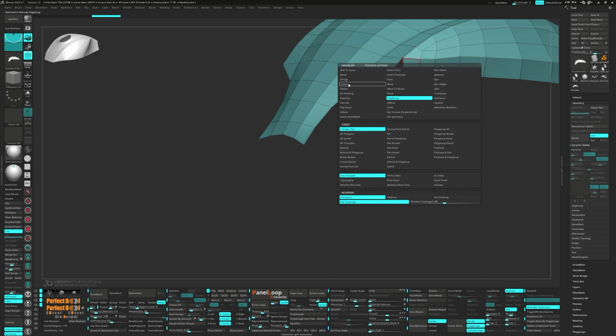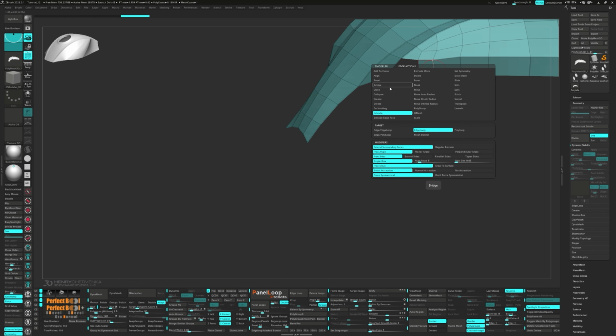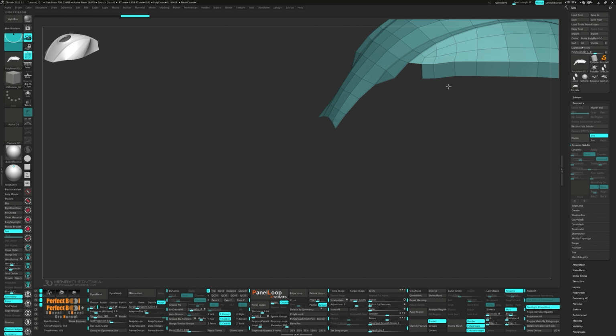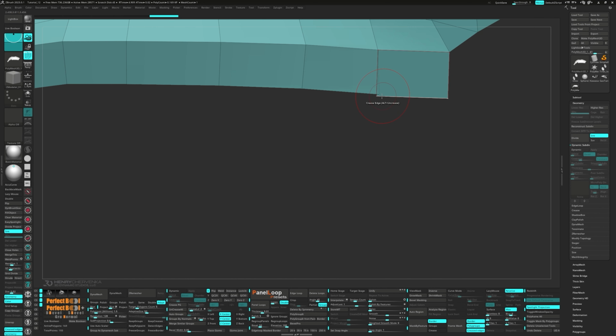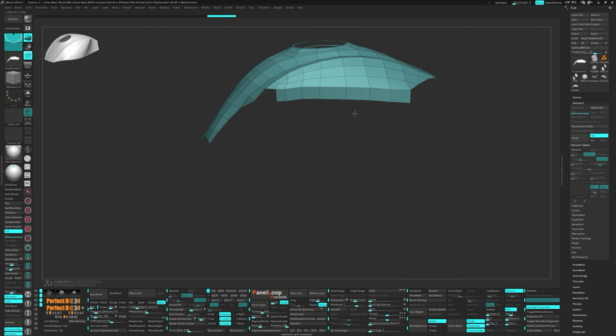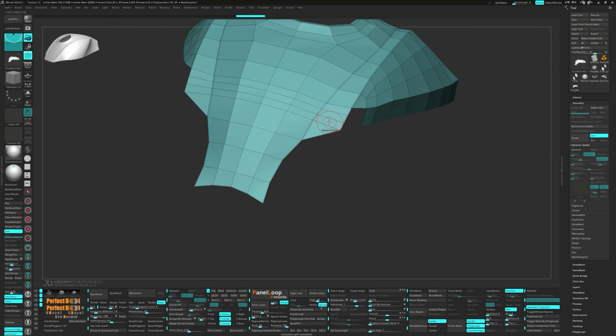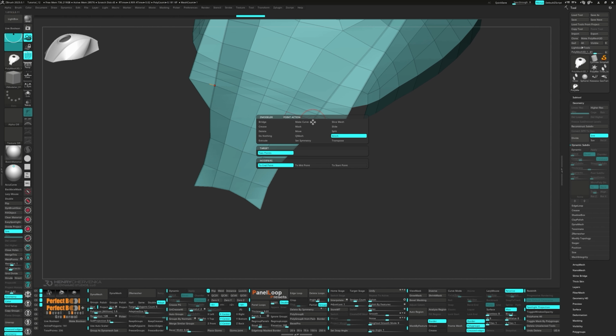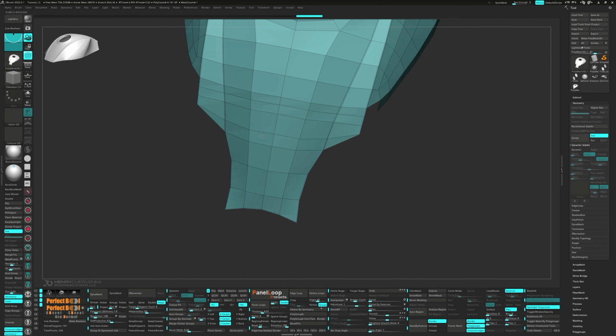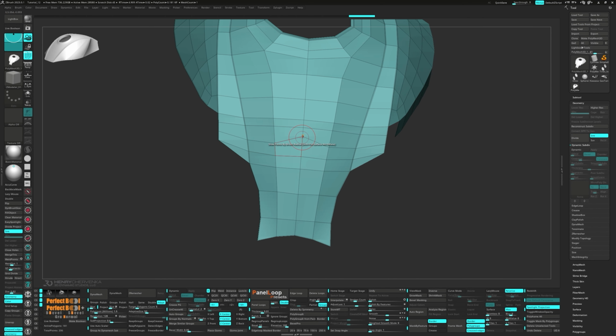Select Delete a single poly, then uncrease the edges. Now choose Stitch for the point action and 2 points for the target. Next, we're going to insert 2 edge loops. Let's turn on symmetry along the x-axis and start spacing out the edges using the slide action for both the edge and point actions.